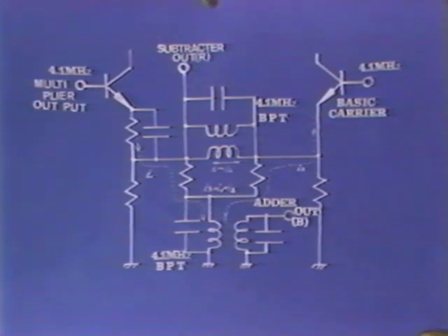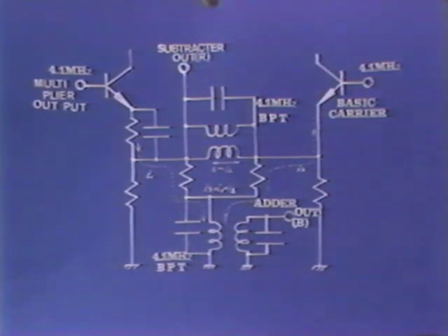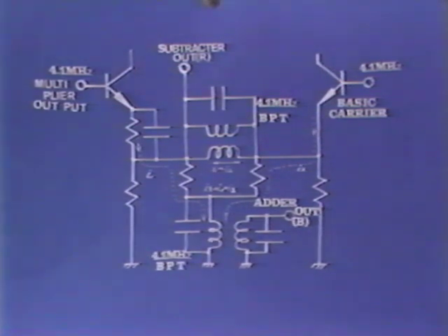This is what is done to separate R and B. At this stage, they are in the 4.1 MHz carrier wave. The following synchronous detectors detect these to pick up the R and B primary color image signals. Here is the actual circuit of the R and B detector.